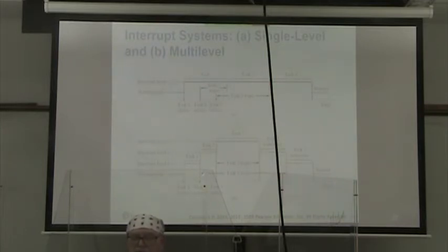When task 3 arrives, it interrupts task 2. Task 3 has the highest priority, so it is completed, and then task 2 goes back to being completed, and then finally task 1 is able to be completed when both tasks 3 and 2 have been finished.